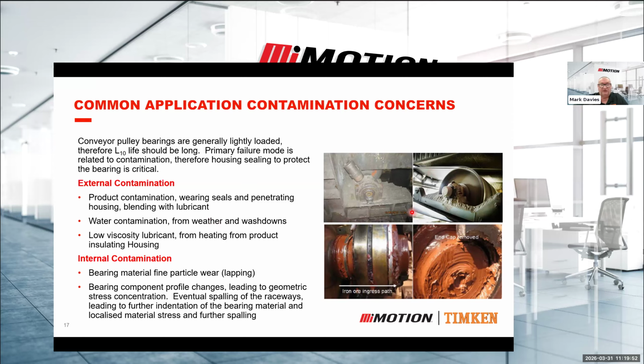Once you do get that product into the housed unit, you end up with a lapping paste inside the lubricant with that fine rock dust, and that grinds material away, and you end up with excessive clearance and damage to the cage. So you quite commonly end up with cage failure as one of the primary failure modes.